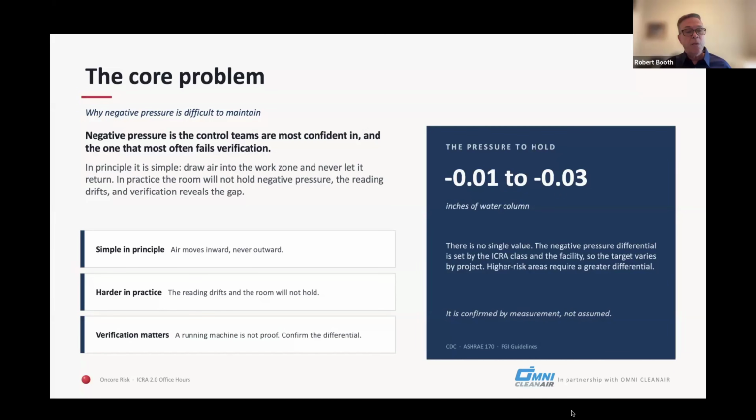And then we also see readings drift back and forth, similar to what we see with an isolation room. It's really up to the organization. Now, I do a lot of litigation, so when I'm looking at this data, I look and see what is the practice that the facility uses to monitor and measure this. Just like we have ORs that have variations in temperature and humidity, we also have variations in pressurization. So the construction area being under complete negative pressurization is what we're trying to achieve.